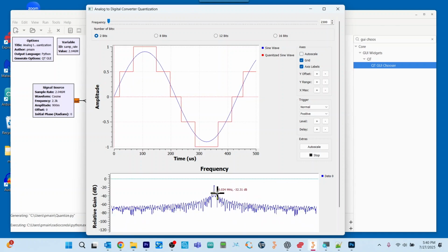Now, all this stuff that you see down at the sides is noise, and more specifically, this is quantization noise. Notice that the highest peak is about minus 35. So the noise is only down about 20 dB.